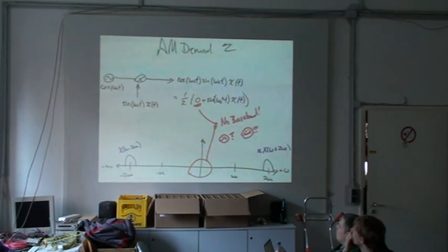So in this example, we've shown a sine wave that's in phase with the original modulating signal. What happens if your demodulating carrier is not in phase with your original modulating signal? Now what? What happens is when you work out the trigonometry, the baseband image just disappeared. It's gone. The harmonic images at twice the carrier frequency are still there. The baseband's gone. And at first you think, oh, that's horrible.